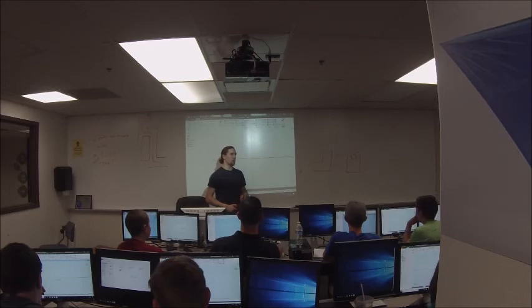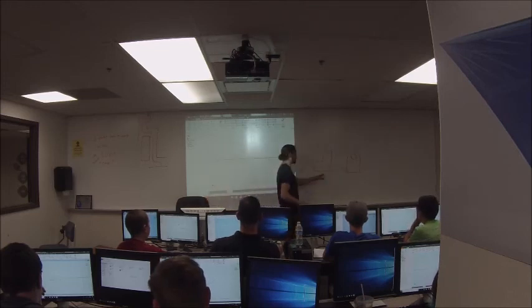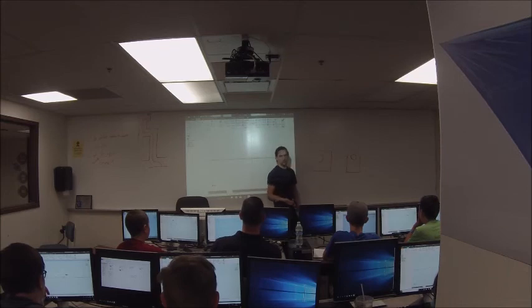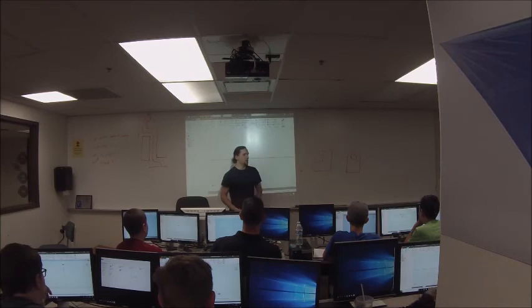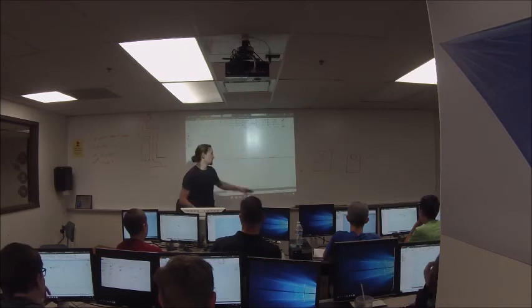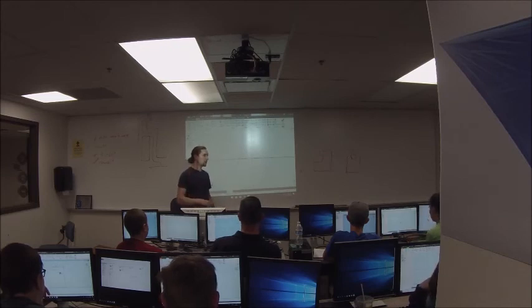Do a horizontal constraint. Also, coincidentally, just in this particular case, because this is a horizontal straight line, you could also do a coincident constraint, click the origin, and click the line. That would work as well. But a horizontal constraint will work between this corner and this corner. So I want you guys to make that sketch, make it any size you want, assign dimensions, but look in the bottom right-hand corner of your screen. It needs to be fully constrained. This one's going to be a little bit more difficult to fully constrain. You have to add a lot of dimensions and constraints to lock it in place.